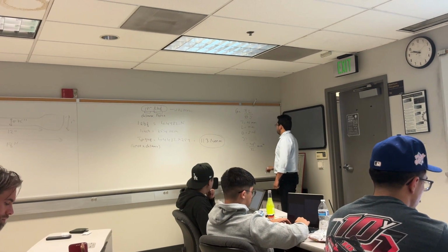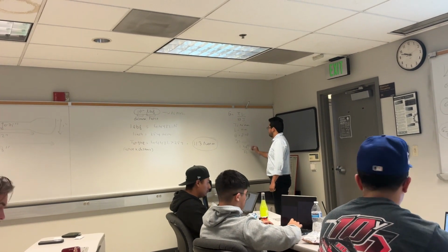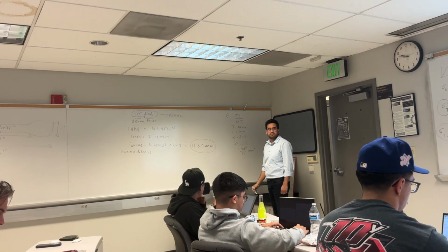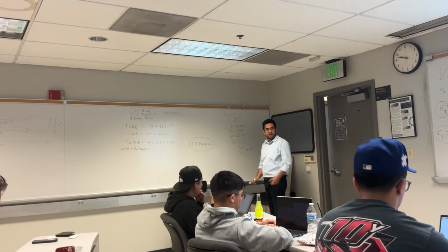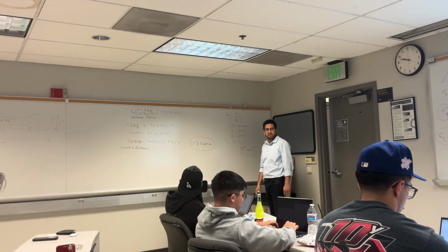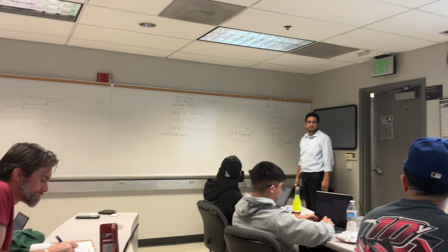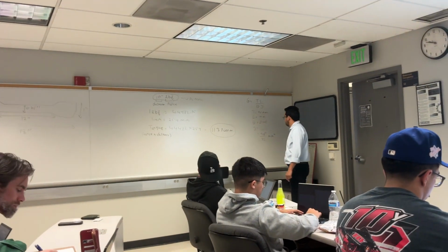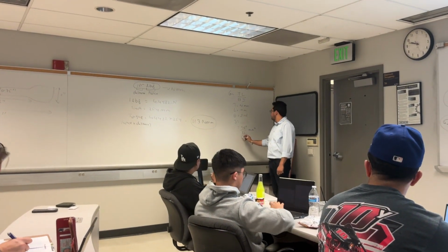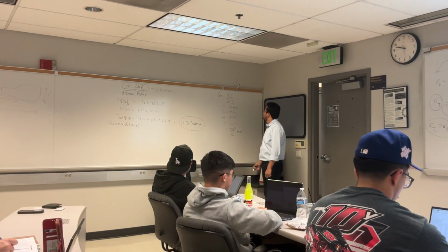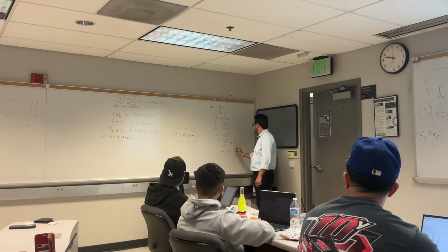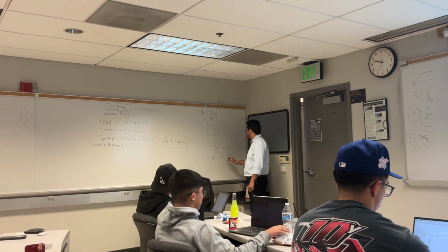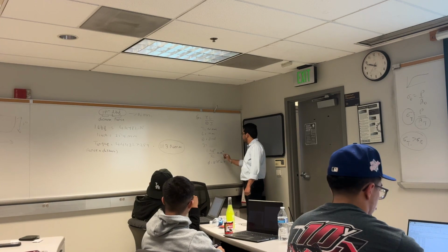D represents diameter, right? Yes. Would we use 0.75 or 1 inch? Only the gauge one. The breakage happens only in the gauge area. So 0.75 is the gripping area. You don't consider the gripping area. So D is 0.75 inch, and you have to convert it into mm before doing all those.